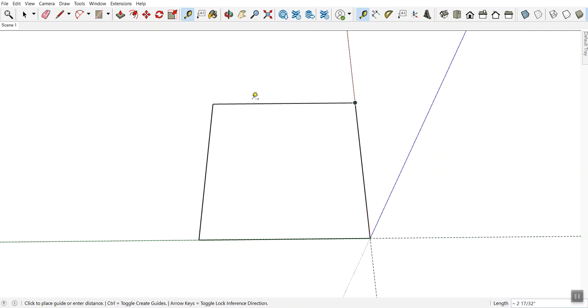And again, we can confirm that by using, for instance, the tape measure. If I put the tape at one corner, it shows 3 1/2. If I go this way with it, it says 3 1/2. And the tape measure is different than dimensioning. Dimension is this one here, which is similar, but it leaves a trace. It leaves the dimension. So now I click it there, drag it to that corner, and then I drag it away. It actually leaves the dimension for me, versus tape, which tells me where I'm at, but it doesn't leave a trace. So if I let go, it'll leave something out there, and it leaves a dotted line, which we're going to use a lot of, but it doesn't leave a dimension like this.